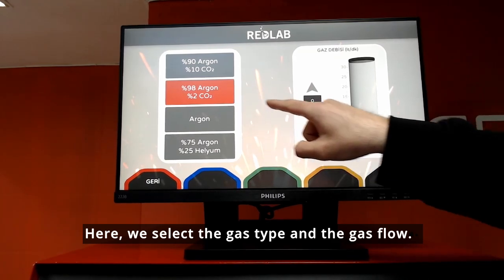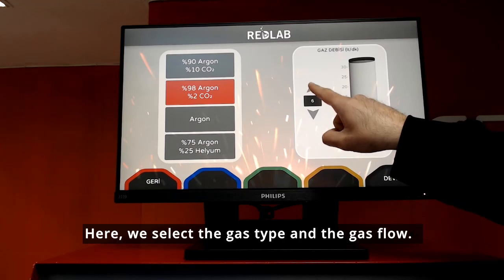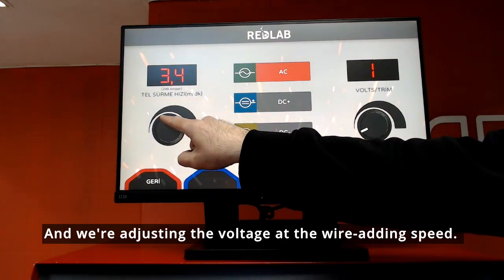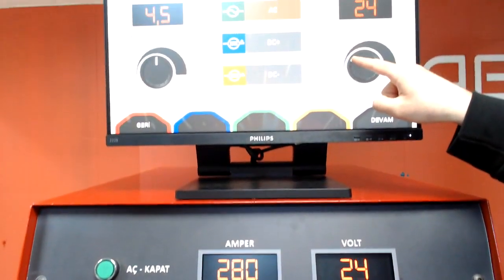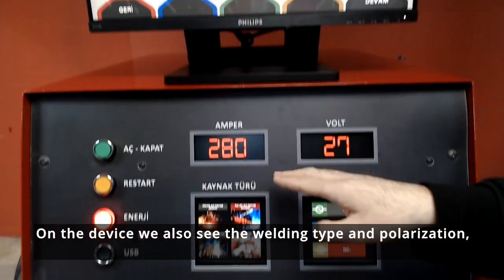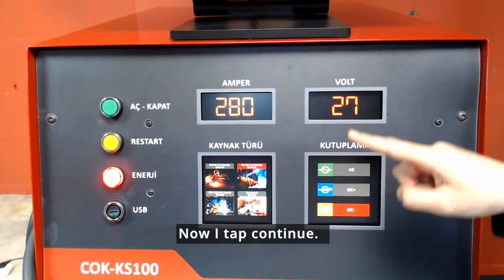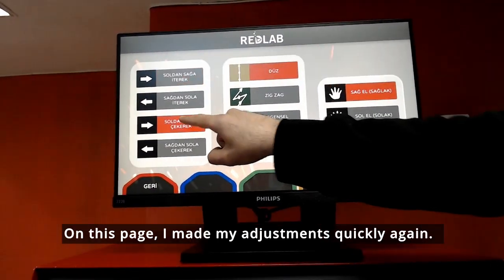Here we select the gas type and the gas flow. And we are adjusting the voltage and the wire feeding speed. And we select polarization. On the device we also see the welding type and polarization, where we select the amperage and volt values. Now I tap continue. On this page I made my adjustments quickly again.